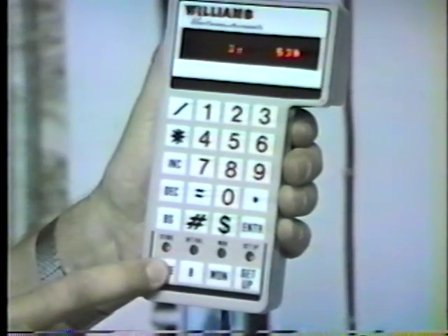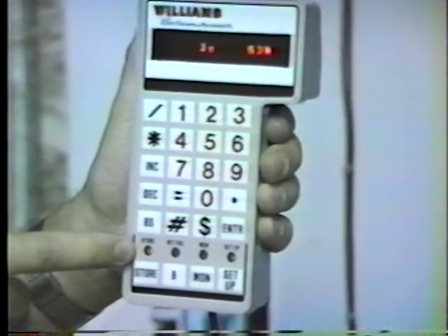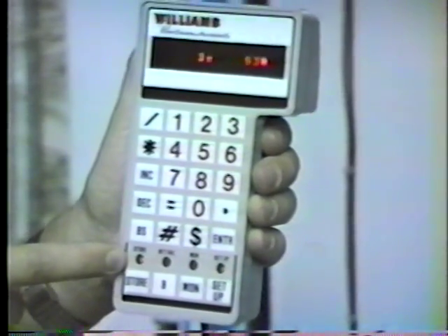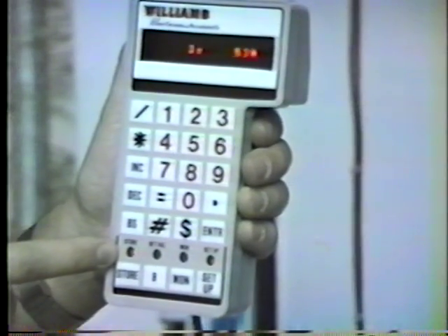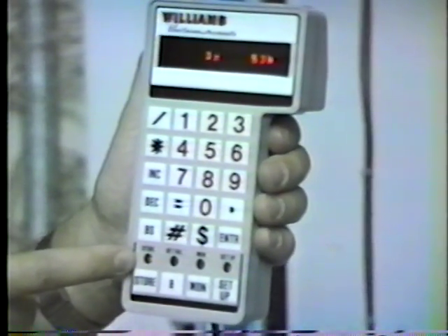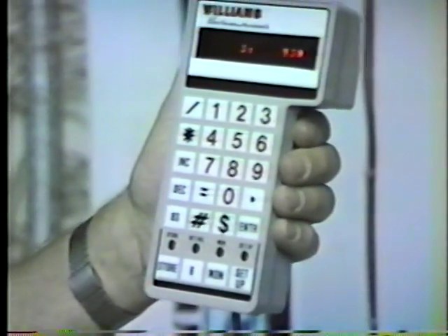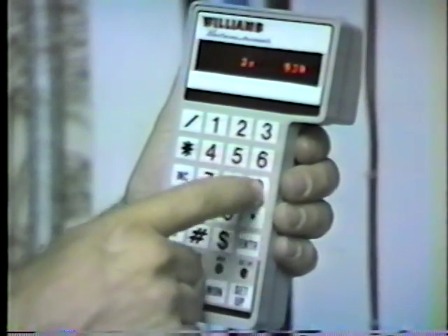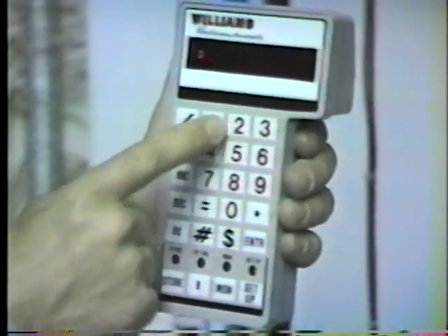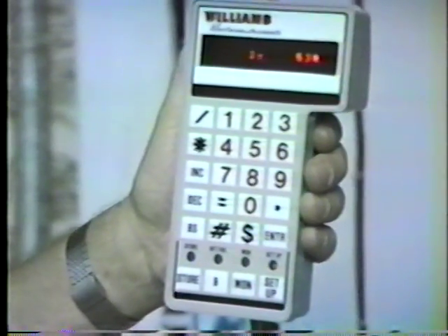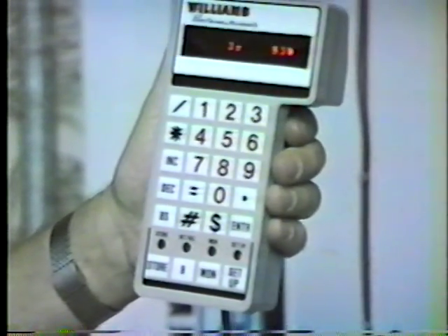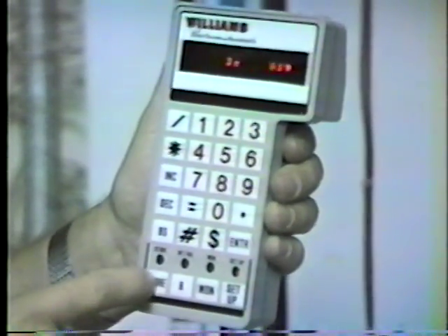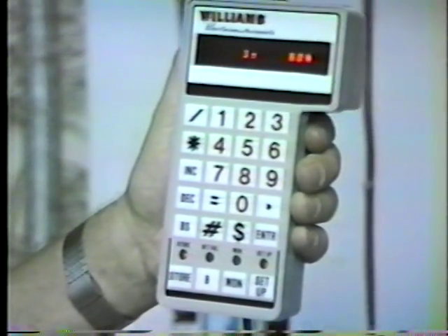When you push store, the store light comes on, and at that point the computer has entered the information into the double EEPROM, the non-volatile memory, and it will remember that even when the power has been turned off. Prove to me that you've actually gotten it in there. If we go to variable 9 and then back to 1, we have 53% in there now. Correct. Would you please set it back properly now? The proper setting will be 72%, as will be shown later. Okay, we're back to where we are.